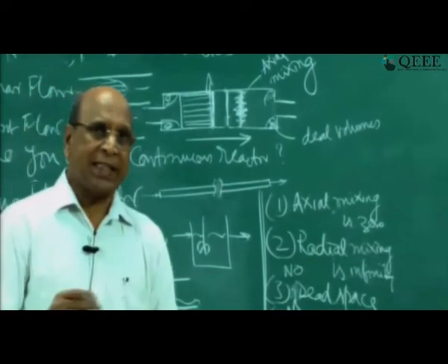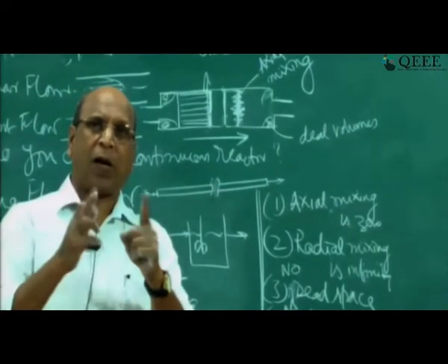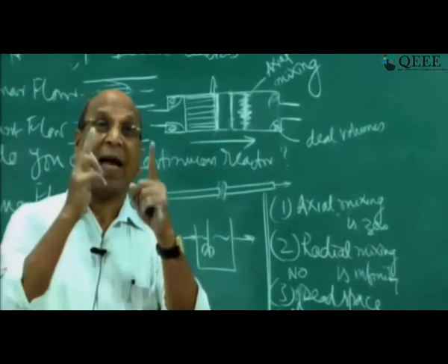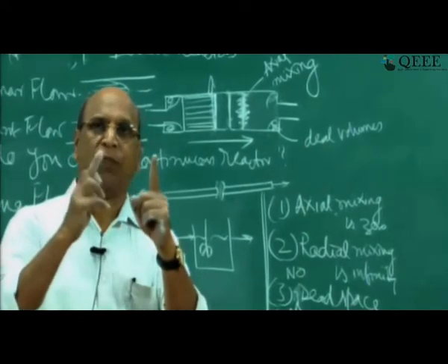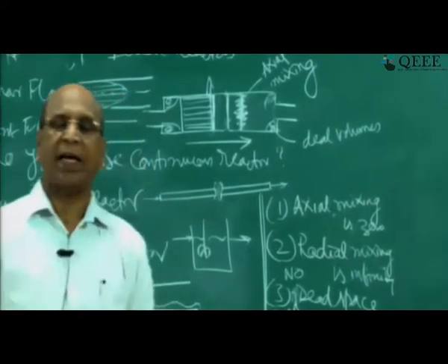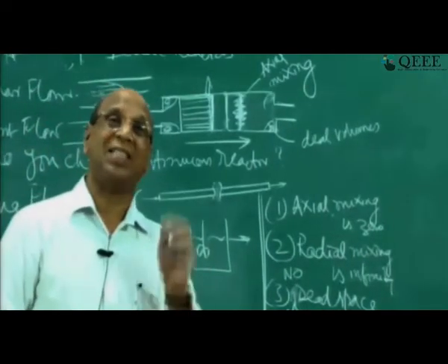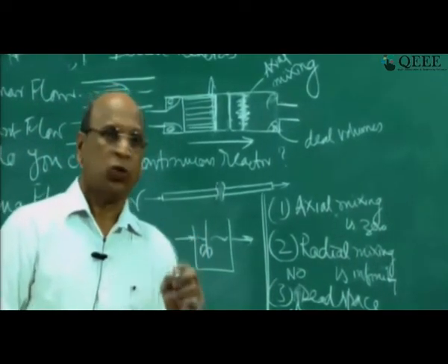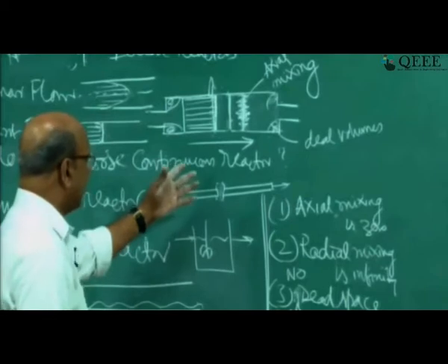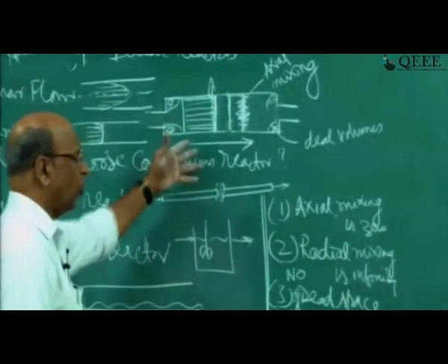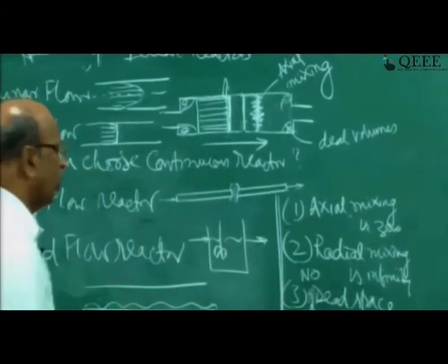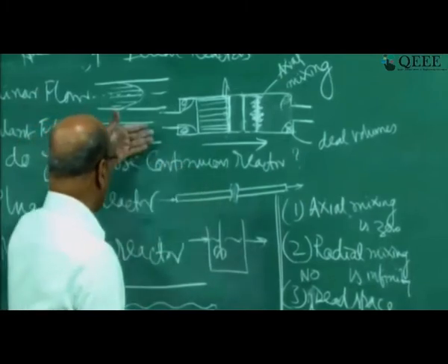So I think this has to be the definition of plug flow: the time spent by each and every particle, every molecule, is exactly the same, right? So when you are writing the material balance, that will reflect. I will also let you know when you are writing the material balance. Okay, good. So that is about the plug flow reactor.